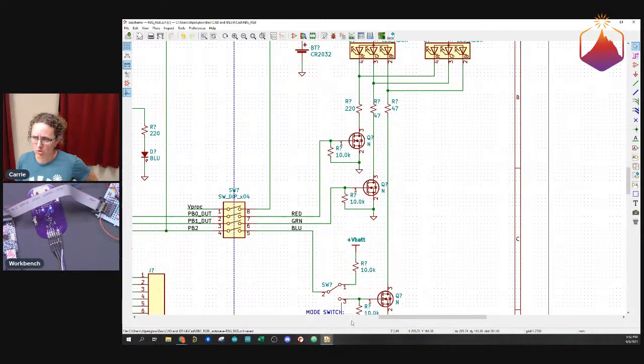So yeah, we have little transistor switches. Basically, when you only have on-off control of something, how do you control the level? How do you get it to appear at half brightness if you only have completely off or completely on at full brightness? Well, you just cycle it super fast. You tell it to be on half the time and off half the time, and you do that thousands of times per second, and your eye averages it for you. So that's how we dim LEDs.